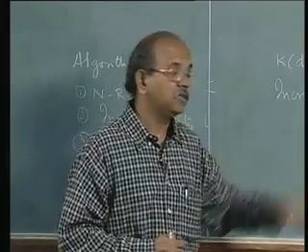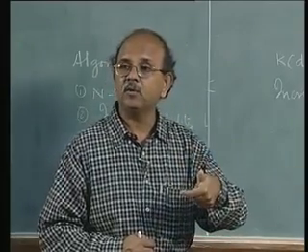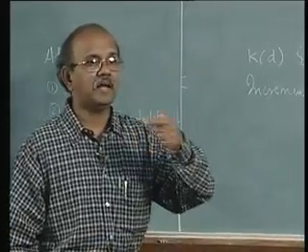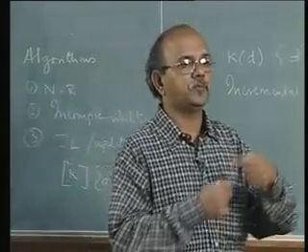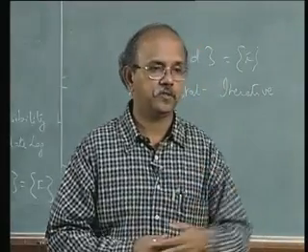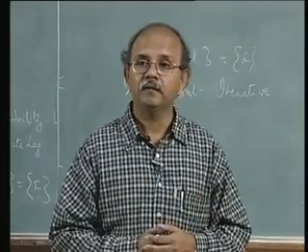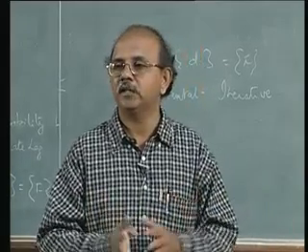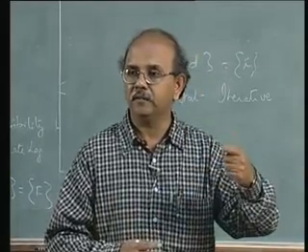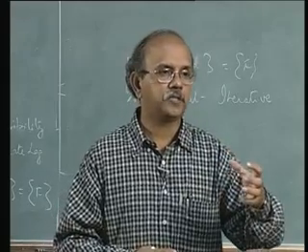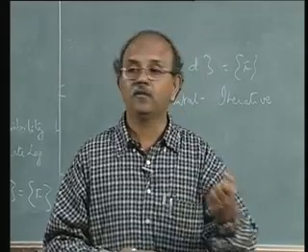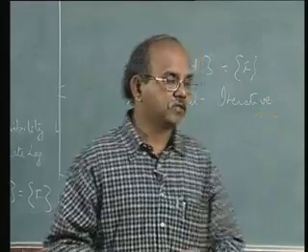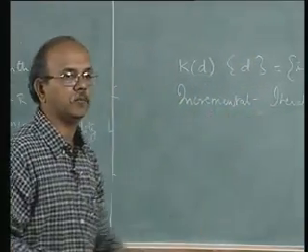What is iteration? As and when I increment the load, I iterate, or in other words, get better and better displacement measures, so that the internal forces are equal to the external forces, or in other words, the body is under equilibrium. So I keep iterating so that the displacements are good enough for me to develop stresses which can hold the external forces. This is what we mean by an incremental iterative approach.